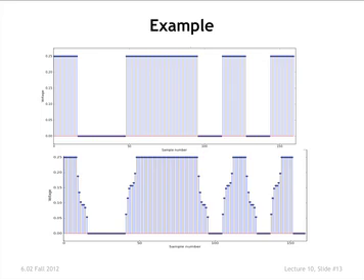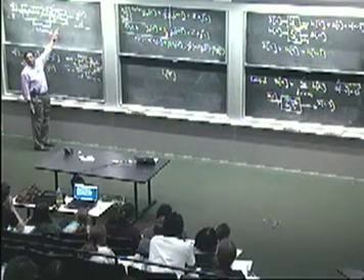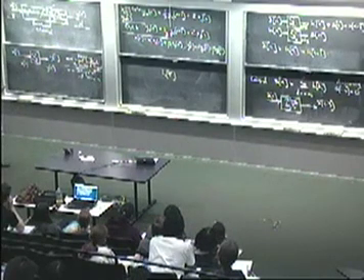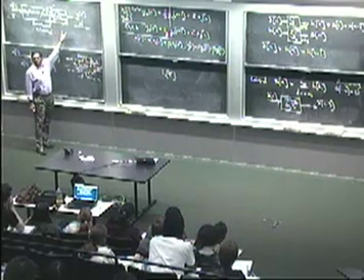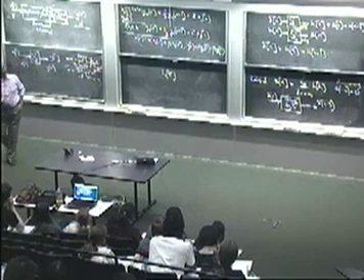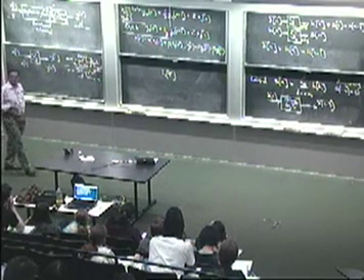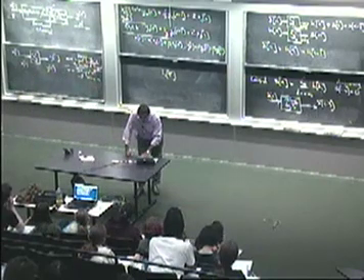It's got a little transient before it settles. So what you're looking at is really the step response of the channel, where the channel includes all these pieces. It's everything including the filtering. In this particular example, if you go back and look at those slides, this was entirely due to the local averaging that we were doing in the filtering here. But it does give you some kind of a distortion. Okay, so the step response is important to figuring out the shape of the output of a channel.